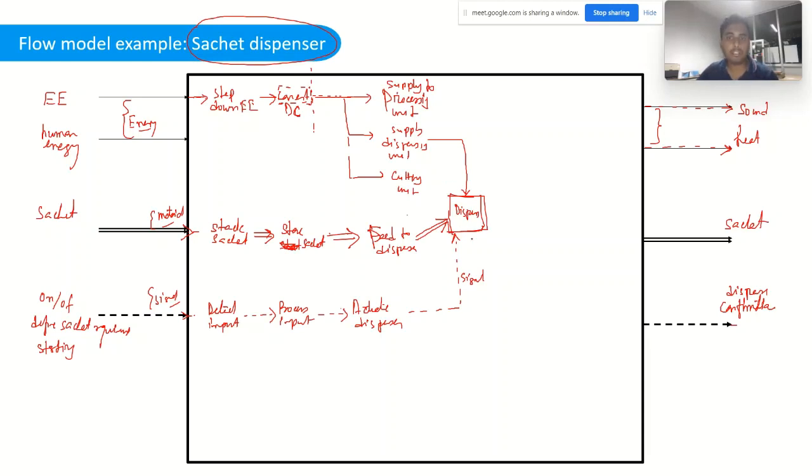What happened? When the dispensing mechanism dispenses, it needs to detect, right? It cannot dispense all the shampoo sachets. It needs to stop at a particular point, so it should detect the count. So after actuating, the next thing is to sense the sachets.